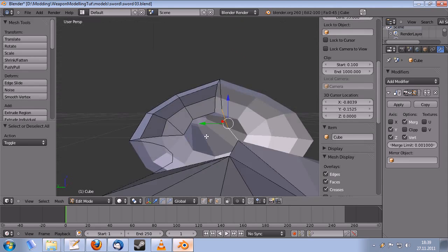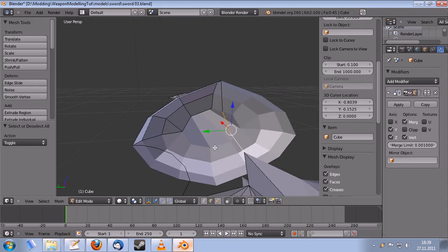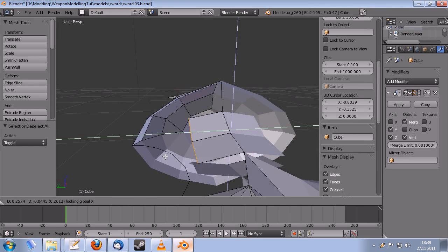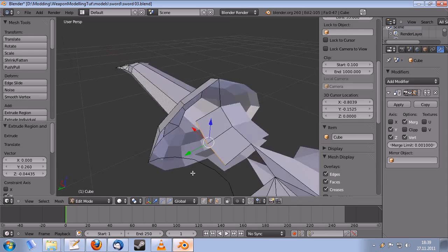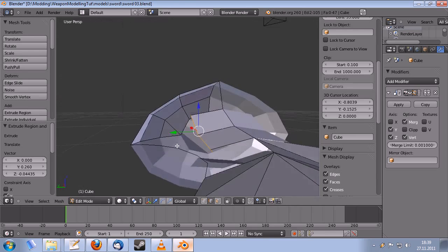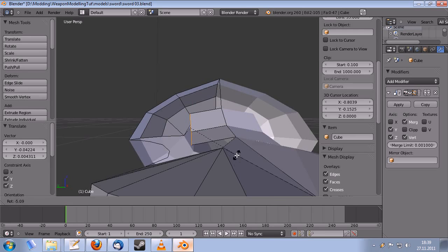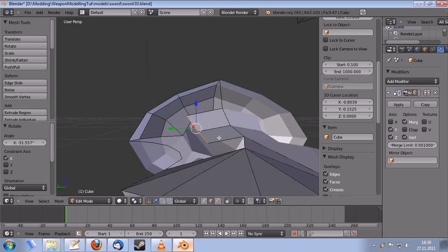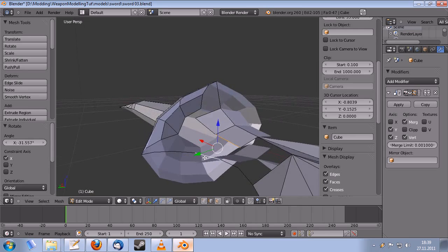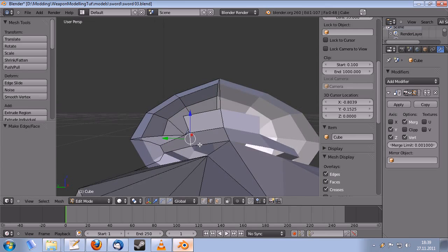I'll just do this in the 3D view this time. Again, Shift X, so it's not moved along X. Also, when rotating you can press X, so it's only rotated around the X-axis. And this is already enough, I believe.